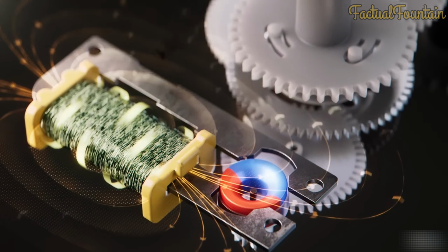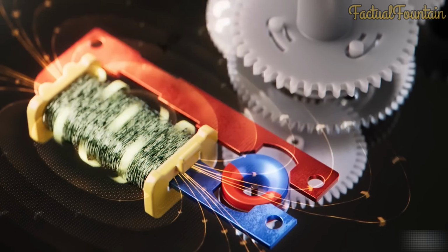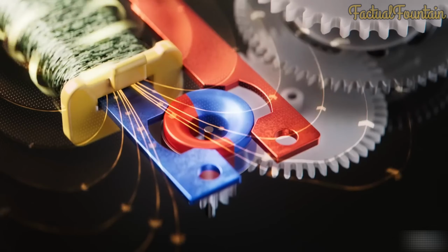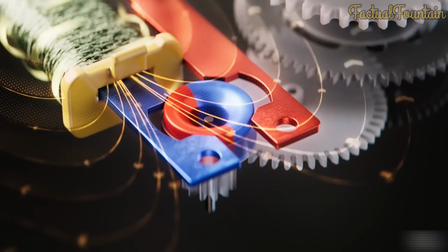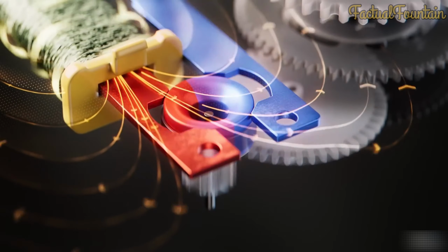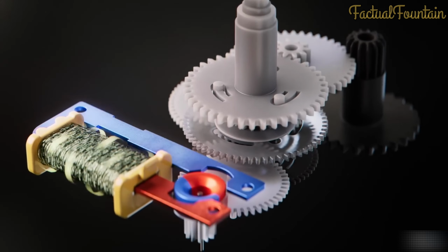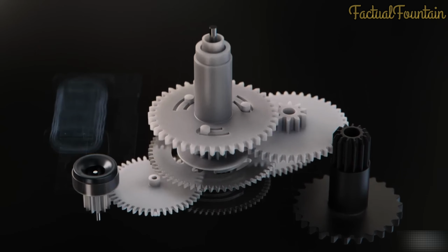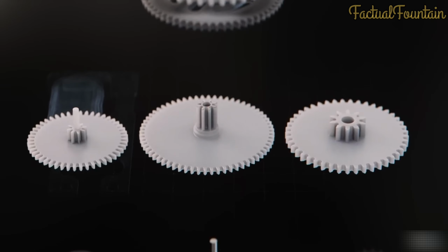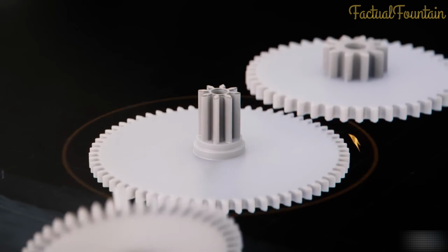Every second, the electromagnet switches directions, thus causing the magnet inside the driver gear to rotate 180 degrees in order to align its permanent magnet with the fields produced by the electromagnet. Therefore, the driver gear rotates fully around once every 2 seconds. Most of the gears in the Geartrain are composed of compound gears, each of which has 2 different gears, one on top of the other.